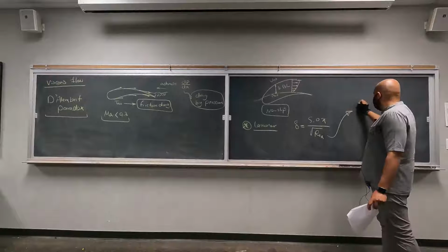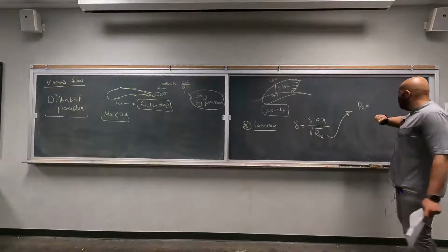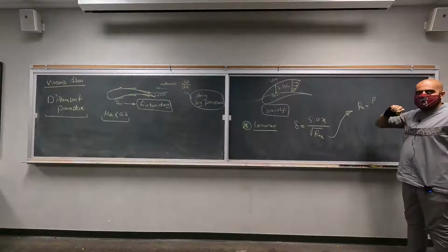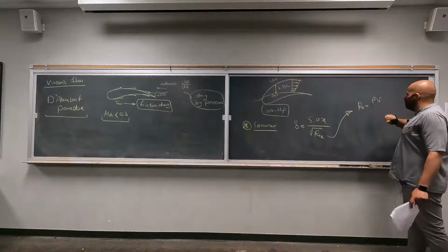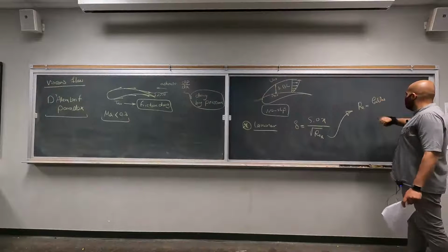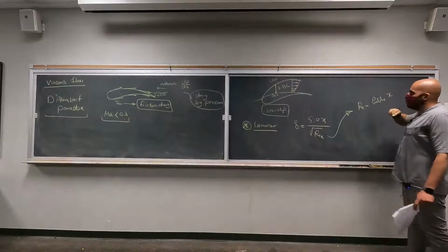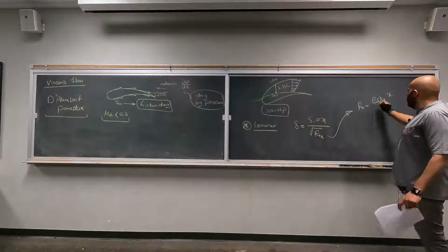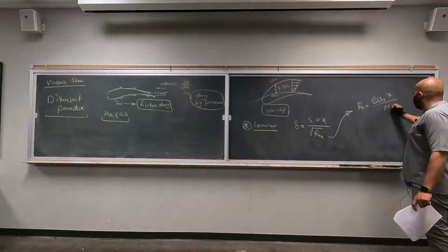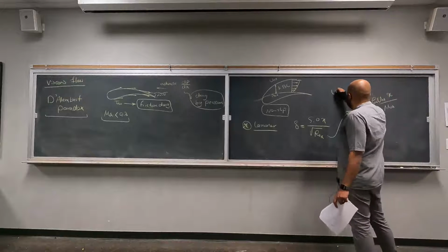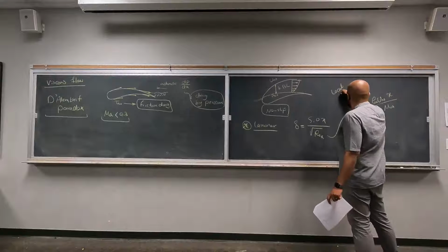Reynolds number on a flat plate is a dimensionless parameter that can be calculated by your free stream density, free stream velocity, let's call it U infinity, the location on the plate, or in this case, airfoil, divided by free stream viscosity. This parameter is called the local Reynolds number.